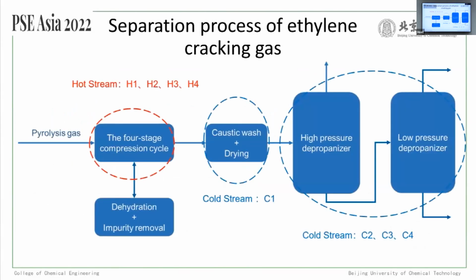In this work, the synthesis of heat exchange network is performed on an ethylene cracking unit in China. Eight mixture streams from the cracking gas cycle and depropanizer are selected due to their large energy demand and room for energy optimization. Specifically, 4 hot and 2 cold streams of them undergo phase transition during heat exchange according to the requirement of the process.